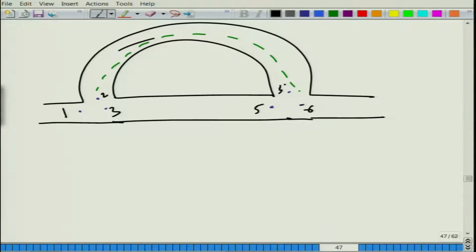And as I briefly talked about in the last few lectures of week 9, this impedance matrix is a beautiful concept, because now we do not have a constraint that the system should have only an even number of ports. It is not necessary that you have a muffler system with only 2 ports, you can have 3 ports also. In such a case, the impedance matrix is very useful for characterizing the system, and then we can do some network analysis, which we are going to do now. So, for a simple 2 port system, and then we will consider another test case.